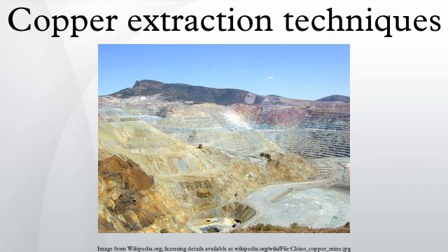The loss of copper as prills suspended in the slag depends on the size of the prills, the viscosity of the slag and the settling time available. Rosenqvist suggested that about half the copper losses to slag were due to suspended prills. The mass of slag generated in the smelting stage depends on the iron content of the material fed into the smelting furnace and the target matte grade.